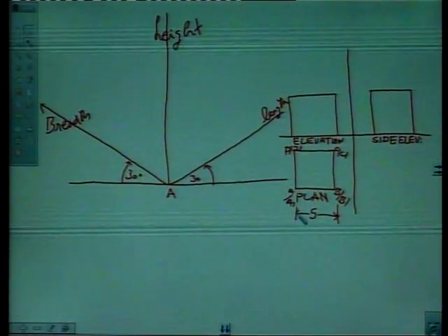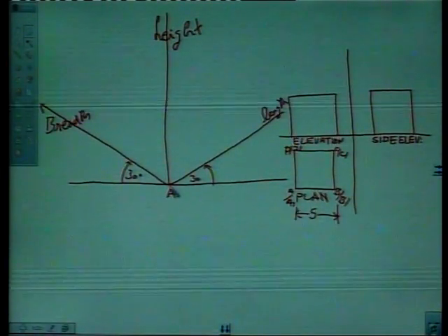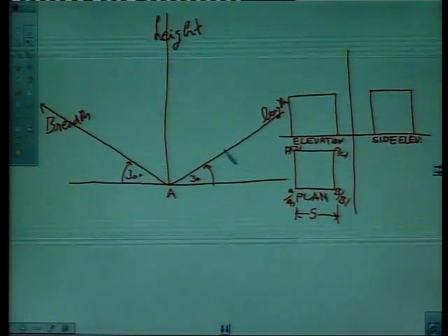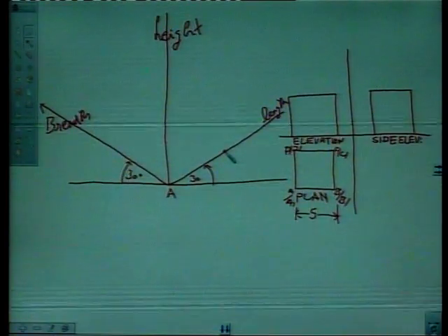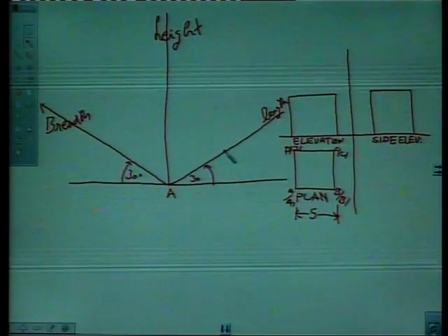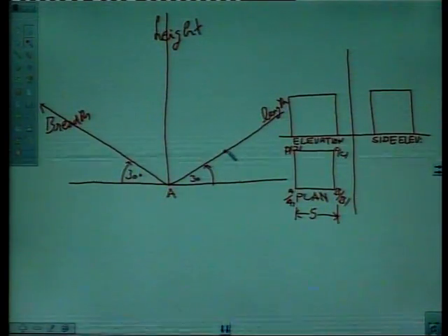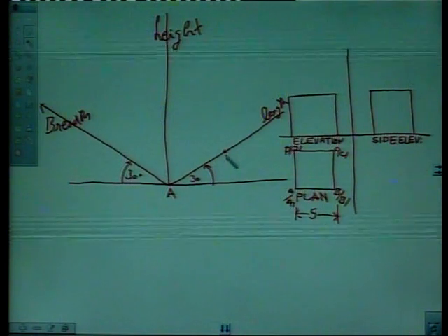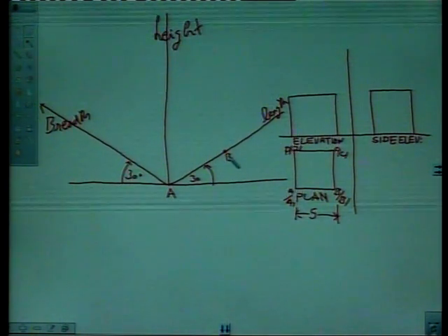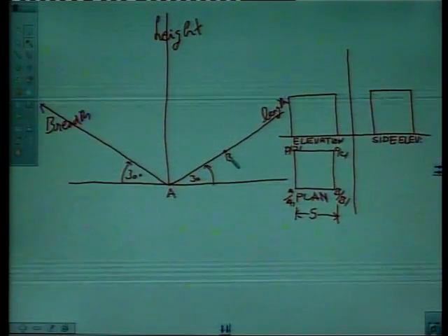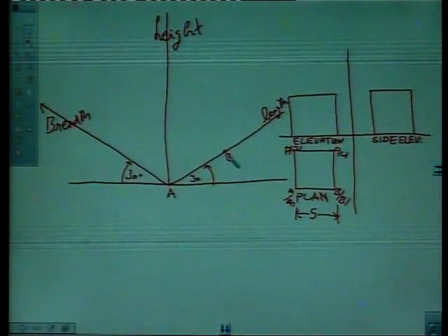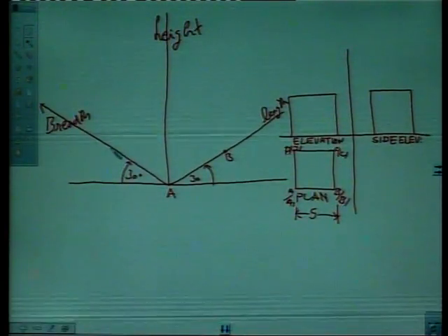So what we will do, we will take from here and mark 5 centimeters. This line represents the length of the cube, which is 5. So mark a point here, A to say B, and this distance is 5 centimeter. Breadth of the cube will be again 5 centimeters, say from A to D. Mark breadth on the breadth line.